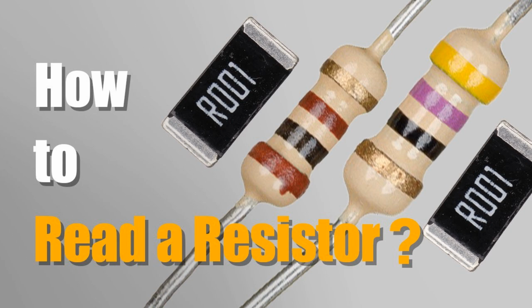Example: a second-order low-pass filter has a roll-off of 12 dB per octave, while a fourth-order filter has a roll-off of 24 dB per octave. Bandwidth. In bandpass and bandstop filters, the bandwidth is the range of frequencies that the filter affects. It is defined by the difference between the upper and lower cutoff frequencies. Q factor, quality factor. A measure of how selective a filter is, particularly in bandpass and notch filters. A higher Q factor means a narrower bandwidth, making the filter more selective.